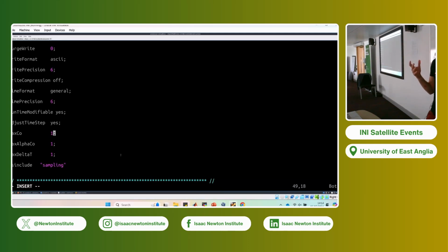So a Courant number of 1 means that the fluid moves 1 cell in 1 time instant, which is a bit too much for a volume of fluid. Basilisk uses 0.5. So in any meaningful simulation, I would suggest to use a value much smaller than 1. But OpenFOAM is set also to try to work with higher Courant numbers if the two-phase flow simulation works well.